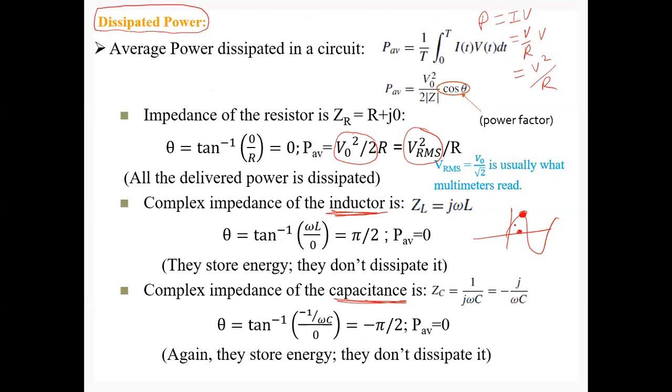You take something in between. What is that called? VRMS. Most of the devices are multimeters, right? Remember we have a multimeter in the lab. That multimeter reads this VRMS. When you measure your AC voltage, your multimeter does not fluctuate like AC. It will give you a constant value. That constant value is VRMS.